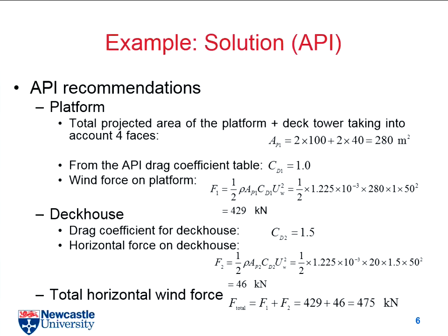The reason is, for this structure, we assume that it's a porous structure, and the wind is coming from this way, and after acting on the surface here, it will go through the structure and act on the backside again, right? It means if the acting area is 100, we need to consider twice the face area. And then because it's a porous structure, it will generate a lot of turbulence. It means this part of effect we cannot ignore.